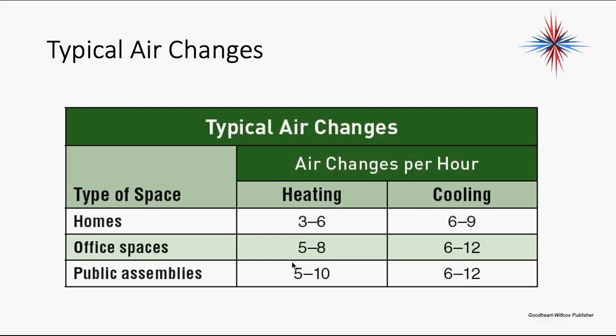When I'm cooling and I'm having to bring in almost 25% outside airflow, we're cooling a lot of extra air with sometimes very high humidity. It's very expensive. So a lot of times you're going to be asked as a technician to close down the outside air and cut off that outside air, especially if there's a landlord that's responsible for energy costs.